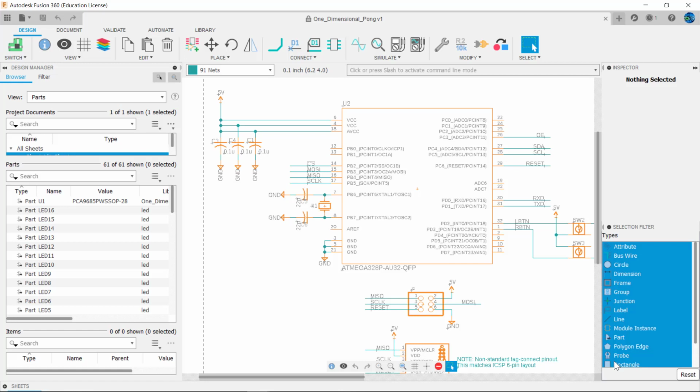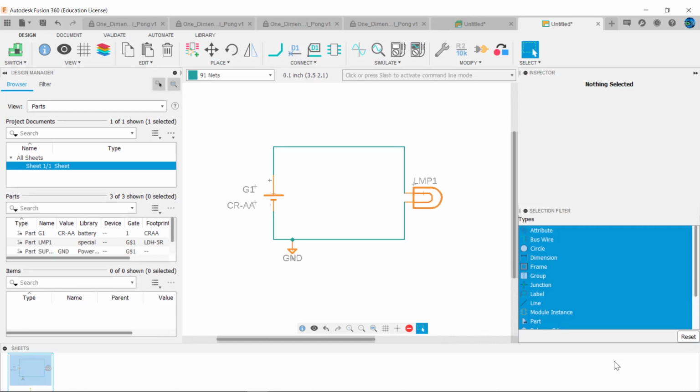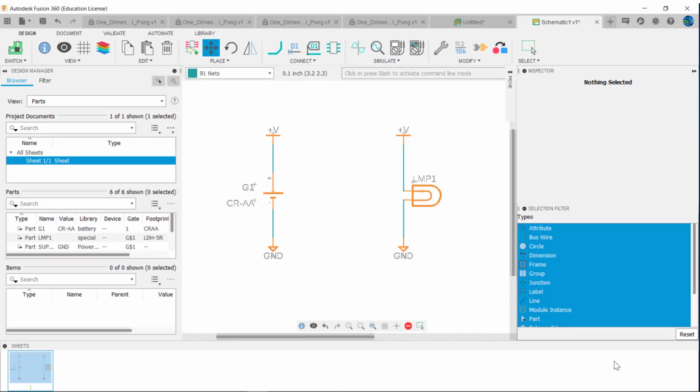So why do Fusion schematics, or for that matter any schematic, look so different? Well, partly it's because of shortcuts we use for power sources. The negative terminal of the power source in most circuits is called ground, and we represent that using the ground symbol. And the supply rail, or terminal as it's sometimes called, is replaced by a supply rail power symbol. Supply connections are often just shown as a connection to a supply symbol. This declutters schematics and makes them easier to follow.